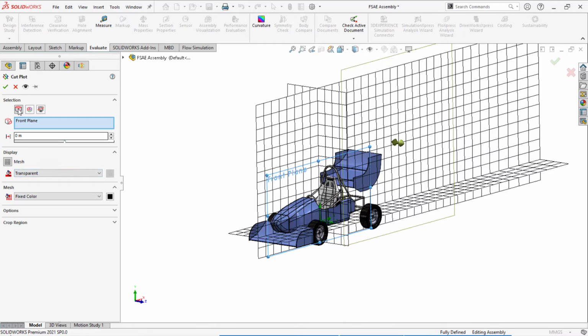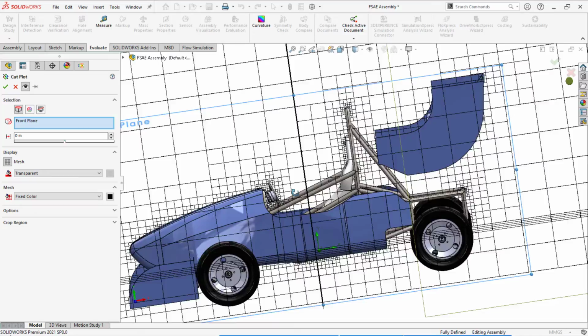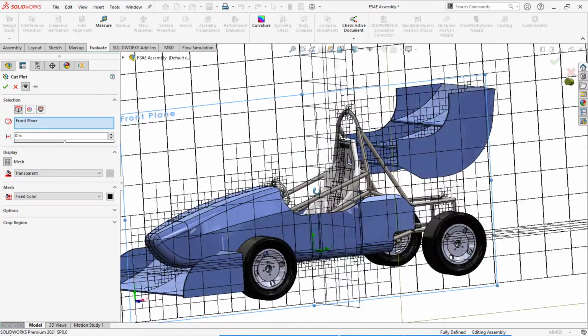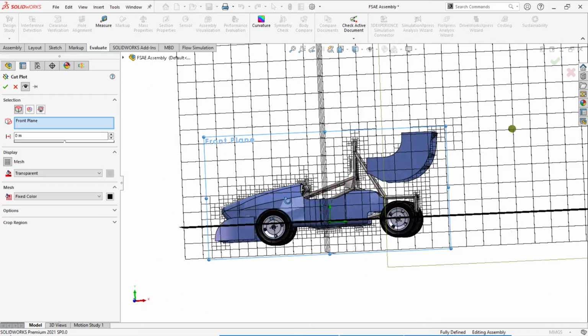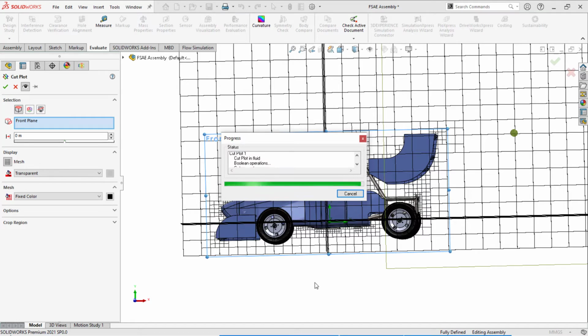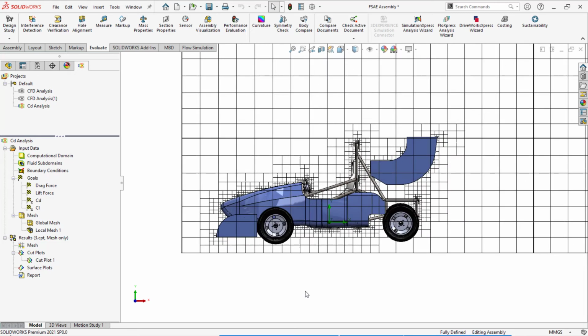So you can just use the show option. This will show you the advanced mesh refinement at the curved regions. Can you see how refined it is? If you want to refine even more, you can do it, but it is time consuming, remember that. So this is how you can deal with the advanced meshing. Very important thing.